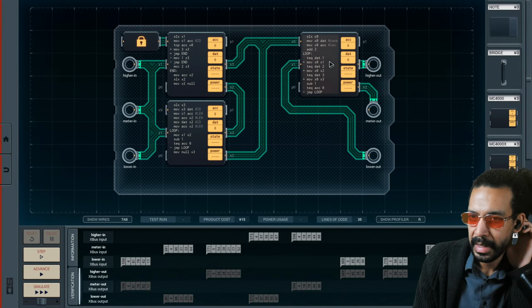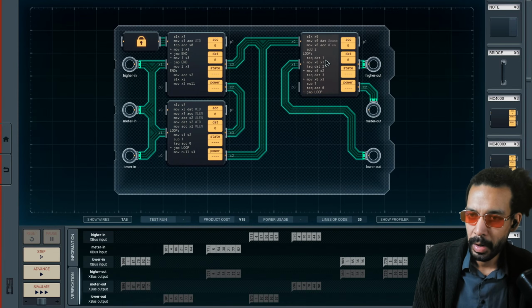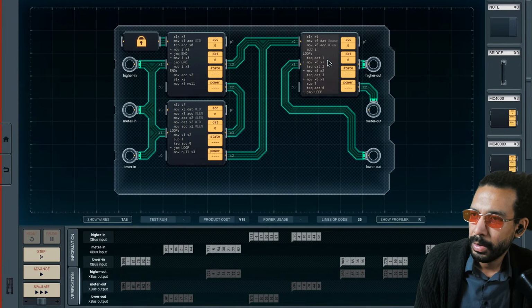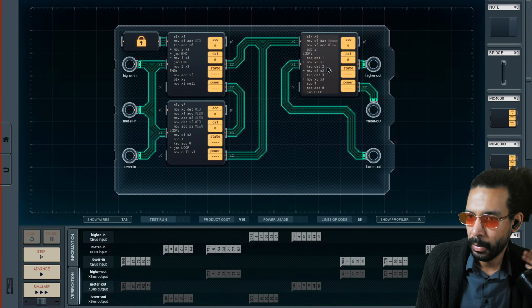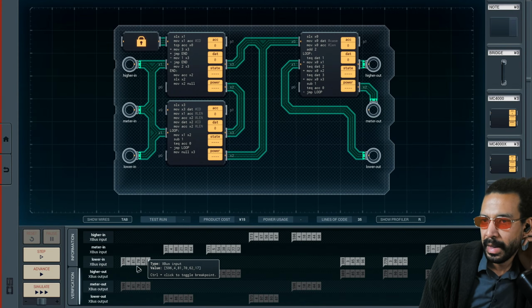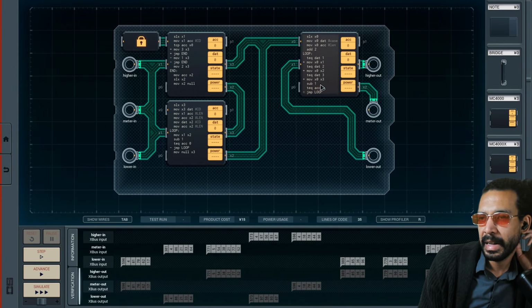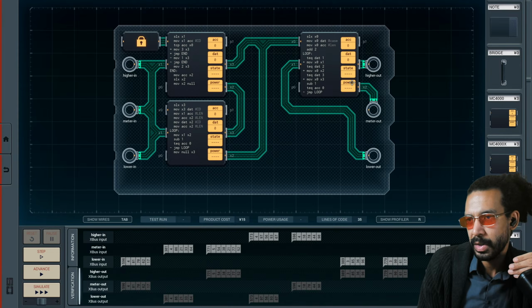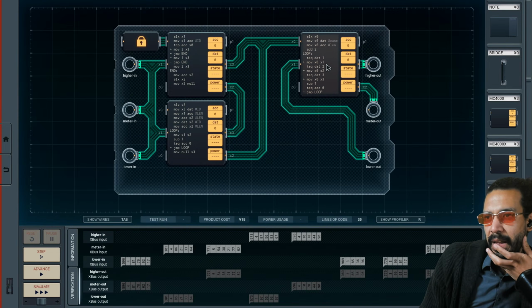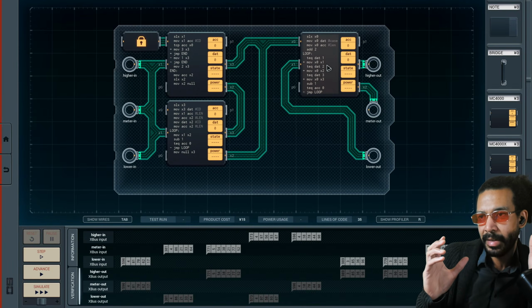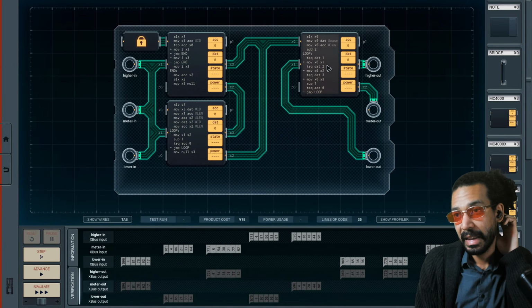All this loop does is check what our case is, 1, 2, or 3, meaning we're less than, greater than, or the correct ID. And then it passes along all the data it receives straight to where it's supposed to go, and all the data it receives includes the duplicated length.